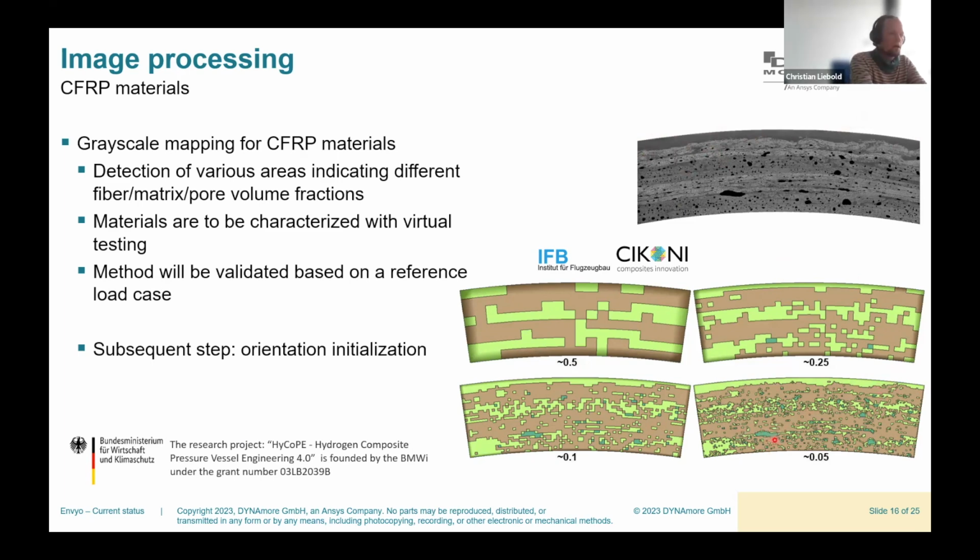And again, the idea behind that is that we do have dedicated material cards for pores and fiber orientations. So each grayscale value gets a specific material card. And with that, we could at least create a validation use case based on a numerical experiment to see if such an approach, going from micro to, let's say, a mesoscopic modeling approach, would help us to predict, on a representative volume area, so to speak, the response of such a material model.